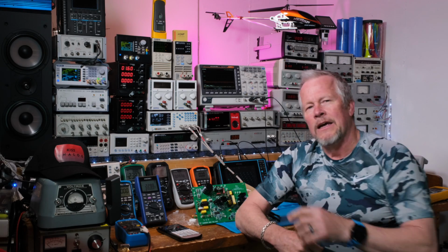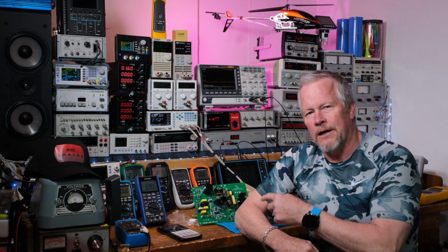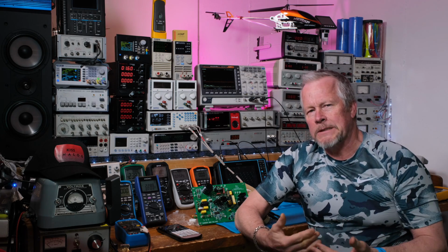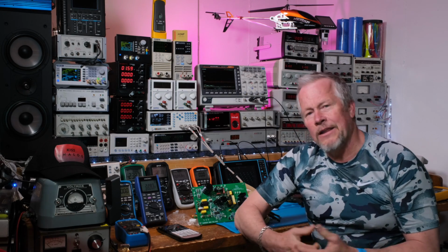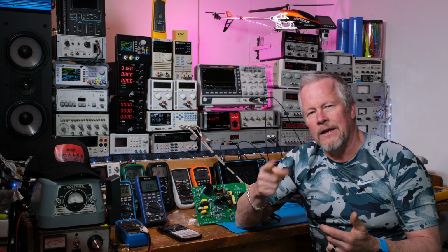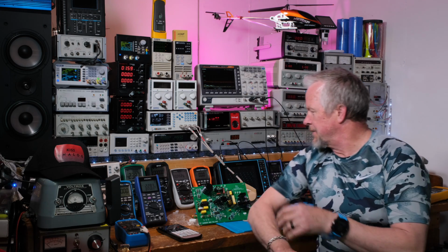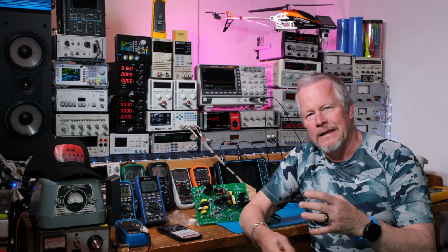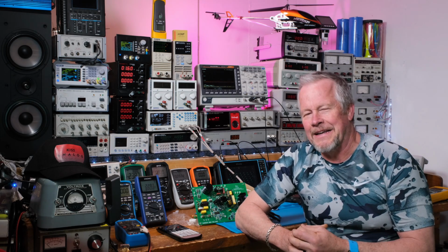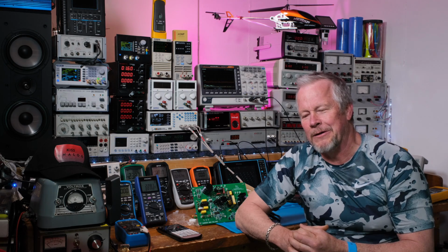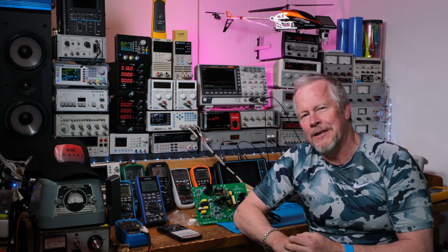So this kind of core and this kind of winding structure that you saw on the board are specifically meant to give you a little bit more differential inductance. And they're actually cheaper to wind, because you can wind those bobbins on the machine and then slide them over the core, versus a toroid that needs kind of a bobbin carrier that winds it. It's a little bit different wind. You can kind of see how that would be a little bit more difficult, right?